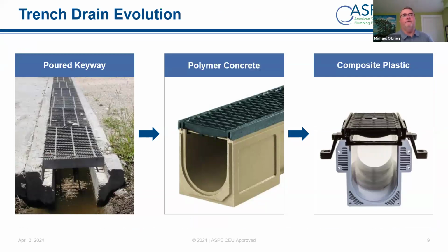So trench drains have evolved over the years. They started out just as a poured keyway. I still see that being used in some places, in some places where it really shouldn't be, but that's where the concrete contractor forms that into the floor, and then they source separately the grates to fill that area. So as you can see, it's not really that pretty. For a parking lot, it's probably fine, but for inside a building, it's not really a good solution.